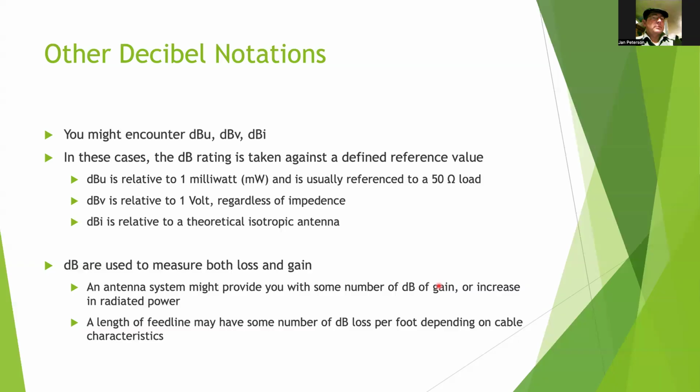With this Yagi antenna, if I'm transmitting, it would come out more in one specific direction, the direction you're pointing it, right? An isotropic antenna would come out in all directions like a sphere, a spherical signal, all equally everywhere around. And the reason we call that theoretical is because it would be really hard to actually build something that did that.